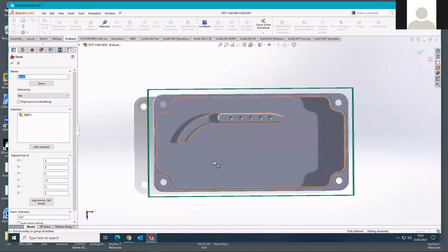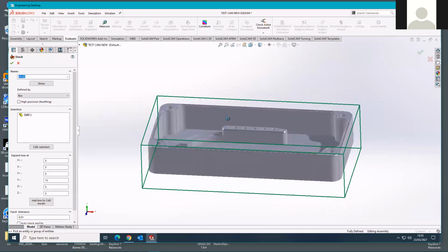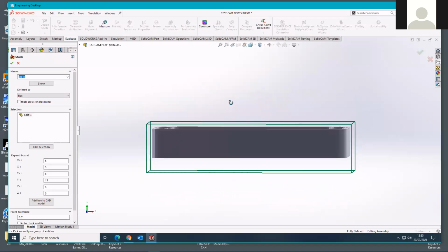So we're looking down onto the internal of the box. So the milling head is coming from this direction, and it's going to be spinning round, taking material out. But in order to do that, I have to come up with some method of clamping my stock block of material to the table of the milling machine. And the way that I've decided to do that is to just use a vise that is itself bolted to the table.